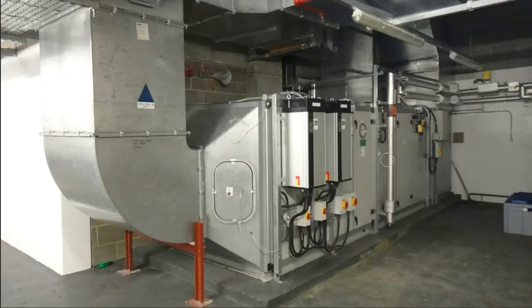And the fan is obviously pushing that, so if you change the speed of the induction motor, if you change the frequency that it's operating at, from 50 or 60 hertz down to 40 hertz maybe, then you'll slow the revolutions of the induction motor down, and that's directly connected to the fan, or maybe not directly coupled.